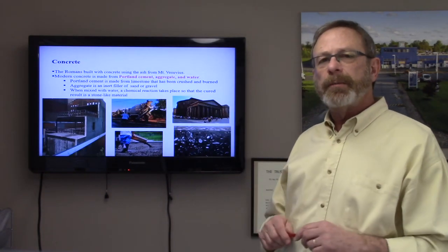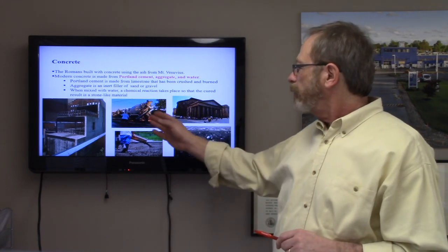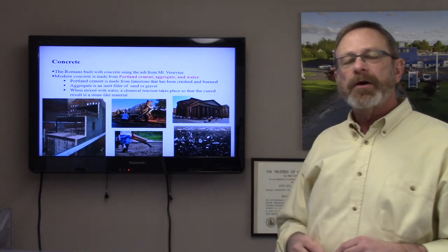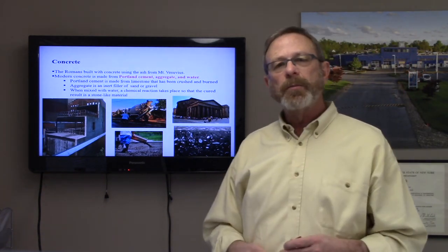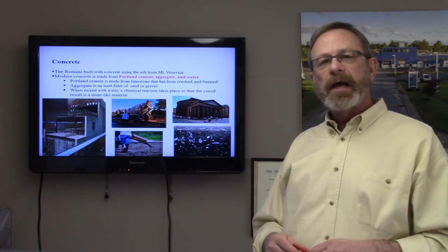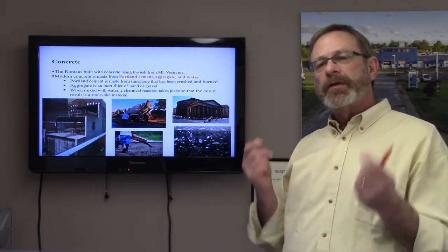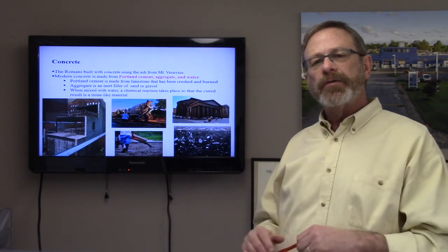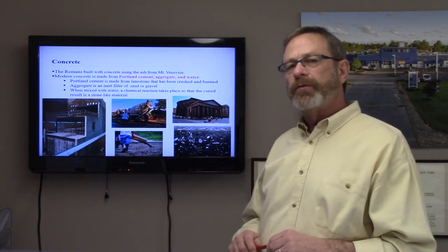So here are some examples of concrete. This is concrete arriving at the job in the truck. Here's a gentleman pouring the concrete in place. The inspector from the third-party testing lab is going to come and pour some of that concrete into one of those cylinders, take the cylinder back, let it dry for 28 days, and then subject it to the test that you last saw in the previous slide.